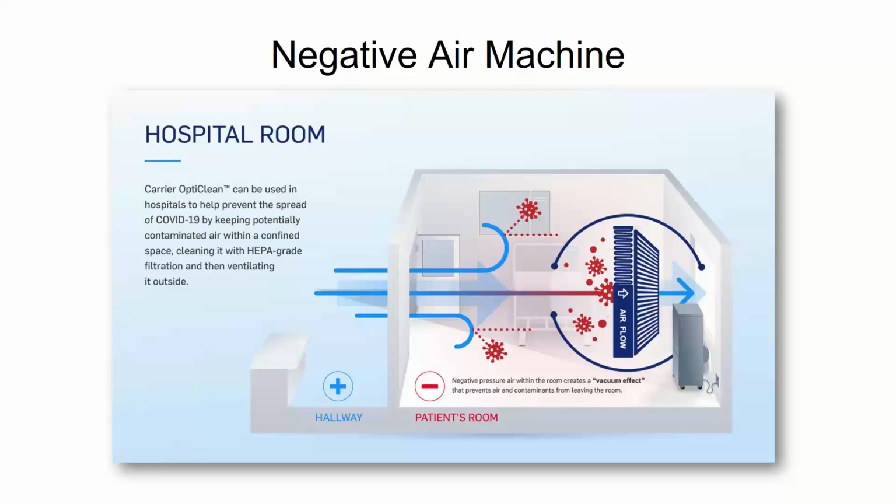So in this case, it's a hospital. It could have been a clean room or something like that. Probably not, but it's a hospital. They want the negative in the room. Actually, it wouldn't be a clean room. Clean room would be the opposite. You wanted that positive. Hospital, I'm going to keep negative because the biggest concern for me is the sick person laying in this bed. I don't want their germs getting into the hallway. I don't want their germs getting into the next room. So I keep their room negative, which means I keep the hallway positive. And then I have some way to exhaust air out of this guy.